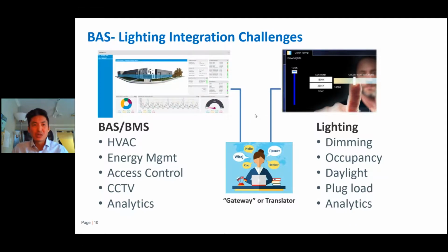So with those two systems, on the BMS side, there's a lot of functionality that needs to happen, and the same thing on the lighting side. In particular, I'm on the lighting side, and there's a commissioning process where you set lighting levels, scenes, and zones. You do the same thing on the BMS side, where you're watching for energy, doing the zoning, and doing profiles for temperatures for certain rooms. And so, do those necessarily meet? Sometimes they do not.